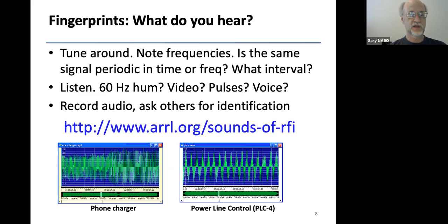Listen to it. What does it sound like? Does it sound like just 60 hertz buzz? That's the old, you take a microphone input and hold your finger on it and you hear that loud buzz. A lot of things generate that kind of noise. Does it sound like video? Many of you probably heard what video sounds like. The pattern changes with the scene, in which case it's related to some television transmission. Maybe it's pulses. Do you hear voice? If there's voice there, well, it's some other, like AM broadcast. That gets into equipment if you live near AM broadcast equipment. Record the audio. Ask other people for identification.